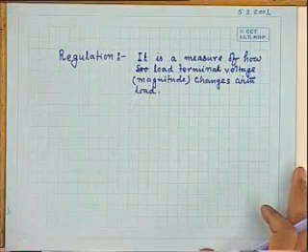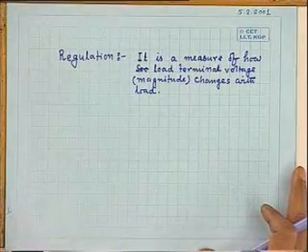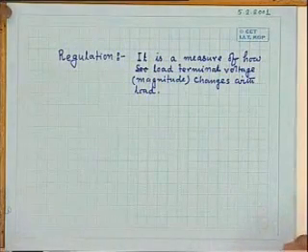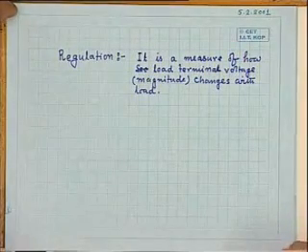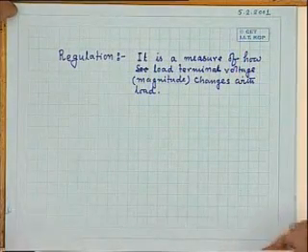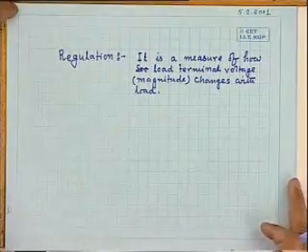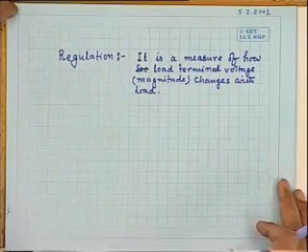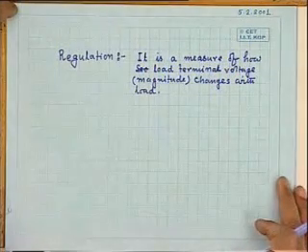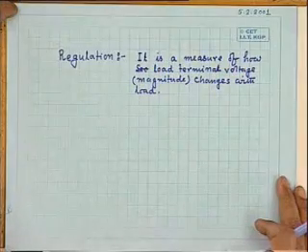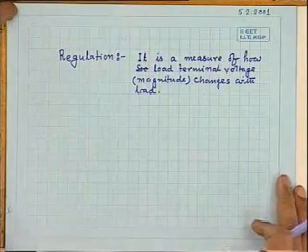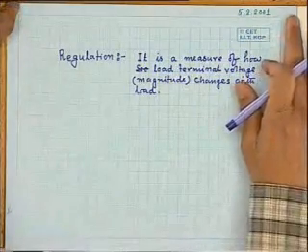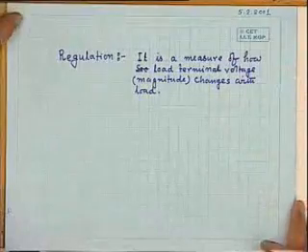As I told you, regulation, or the change of voltage, occurs across the load terminals as you change the load because of the internal impedance of the transformer. And remember, it is only the series impedance, that is the equivalent resistance and leakage reactance, which will cause this voltage drop to take place inside the transformer, and in effect the secondary terminal voltage gets affected as you change the loading. So how to derive a handy expression to calculate the regulation of a transformer will be our today's first topic.